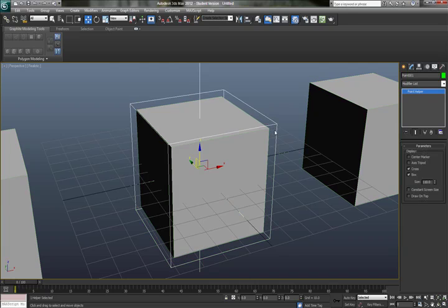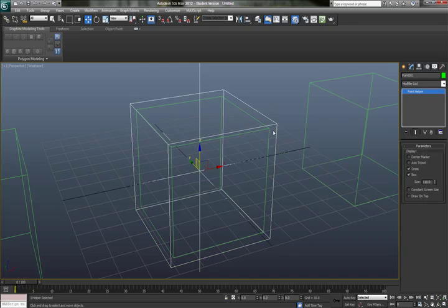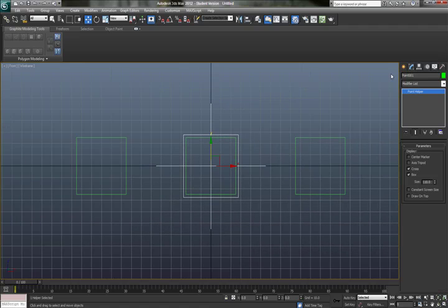So that being the case, back to wireframe view. This time I'm going to be in front view, so I hit F, and you'll notice that when I created this, the name of it is 0.001. Well, one thing I want to do is make sure that I name this root, because this is the central bone which the other ones will be based off of. So the other ones, when they rotate, will rotate around this central one, and when the root bone is moved, we will be able to move all other bones and meshes that are connected to it. So this one is named root.